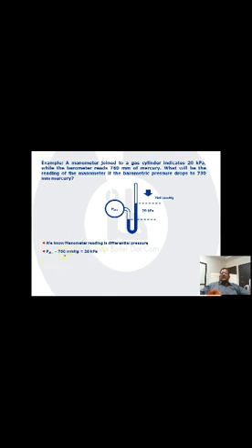Now this is changing by 30 millimeter of Hg, right? So this goes down. Naturally, this goes up. So P absolute minus 730 will be 20 kPa plus 30 mm of Hg. All I need to do is now convert the mm of Hg into kPa, which is done by dividing by 750 to give me bar, multiplied by 100 will give me kilopascal. So the answer will come to 24 kilopascal.